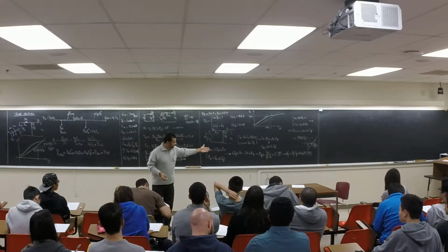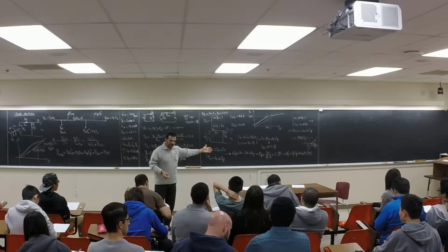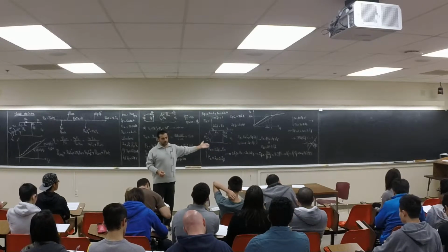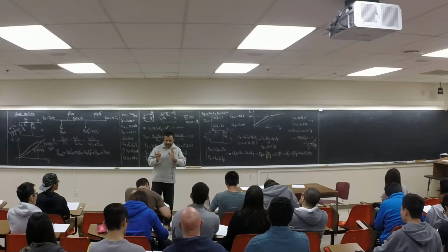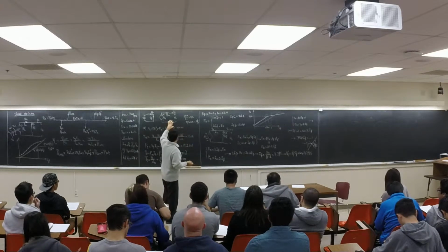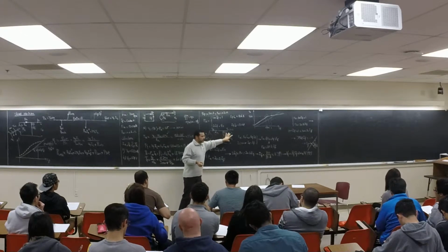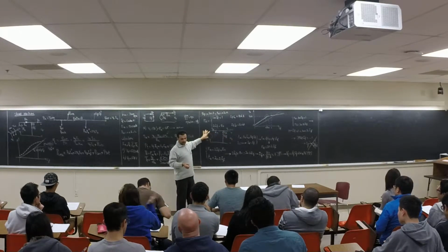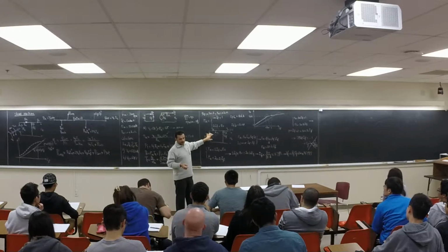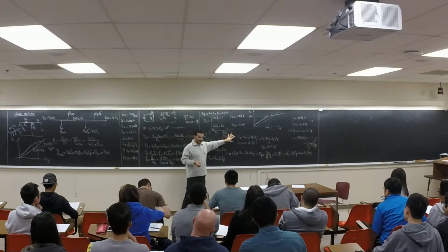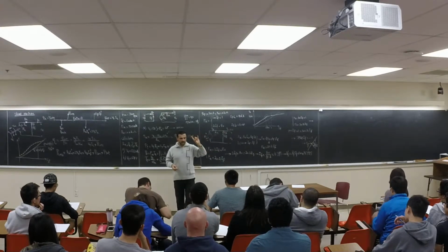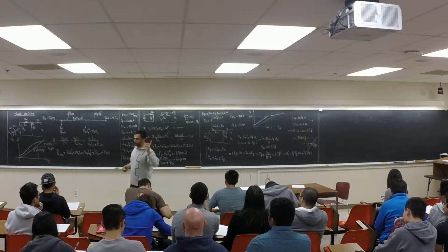If you calculate the VT, you can see that VT is about 84, 85 volt, right? So you're going to have 1 volt over 85 volt. I'm saying under the no load condition, to assume this one is almost equal to this one is pretty accurate. It's not a very big error, right? You can see here, this one is about 85, this one is about 86, right? 1 volt difference, it's a little bit more than 1% error, right?